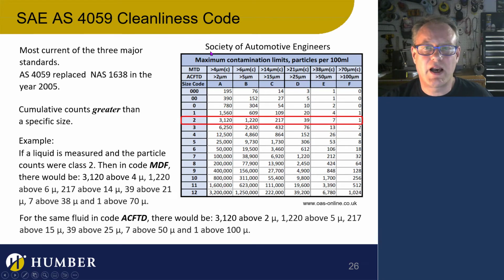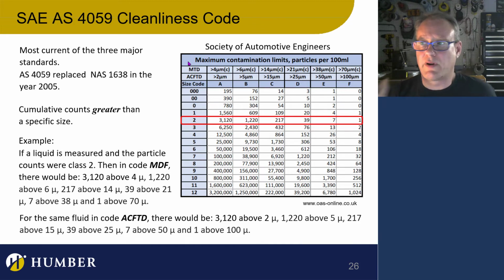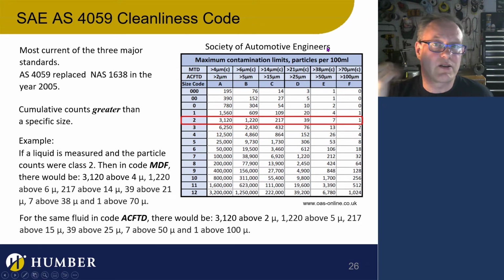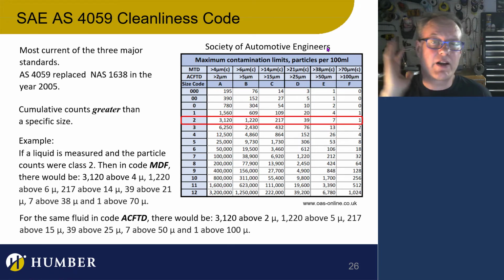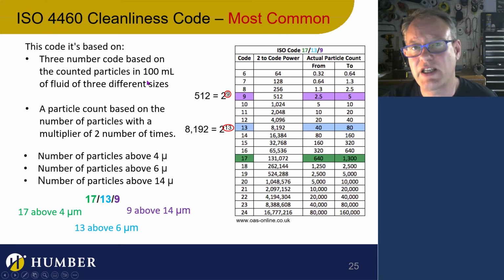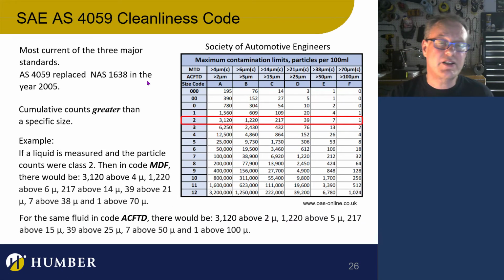So essentially, Society of Automotive Engineers, right? And again, this is a code used for all fluids, whatever, oil, gear oil, hydraulic fluid. The Society of Automotive Engineers came up with this standard. It's a common standard, and you will see it used on hydraulic fluid. You will also find that ISO 4406 is probably the most common. We'll talk about another type of code, which you'll still see on older machines or older equipment.